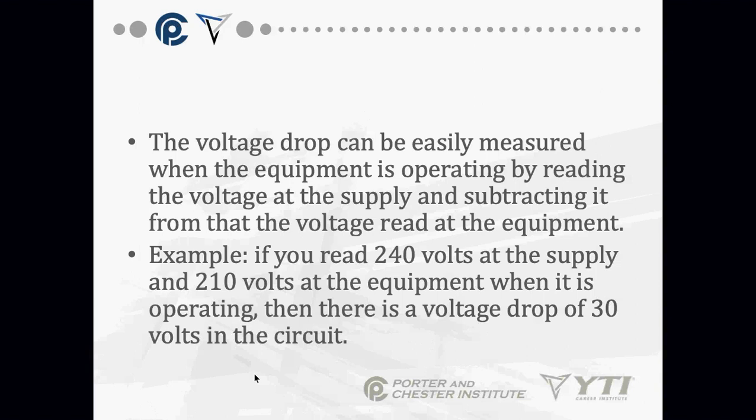Okay, voltage monitors come as test instruments. You can buy them from just about any supply shop, and quite honestly, right now, Amazon has been cheaper than most of the supply shops. Stick a voltage monitor on it. Record it over a 7-day period. If you can catch the voltage, you'd have to leave that at the client. You'd have to leave that at the work site, wherever you're at.